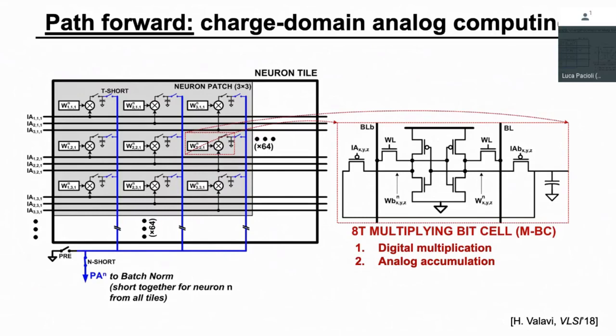And the value of this is the following. How precisely I can do this depends on a capacitor, not a bit cell current. Bit cell currents are messy things. They depend on semiconductor parameters like mobilities, device parameters like threshold voltage variations. Capacitors depend on geometric properties. If I was to bet on something, I'd bet on those. In particular, as technology scales, this is something that can hold up, potentially, needs to be proved.